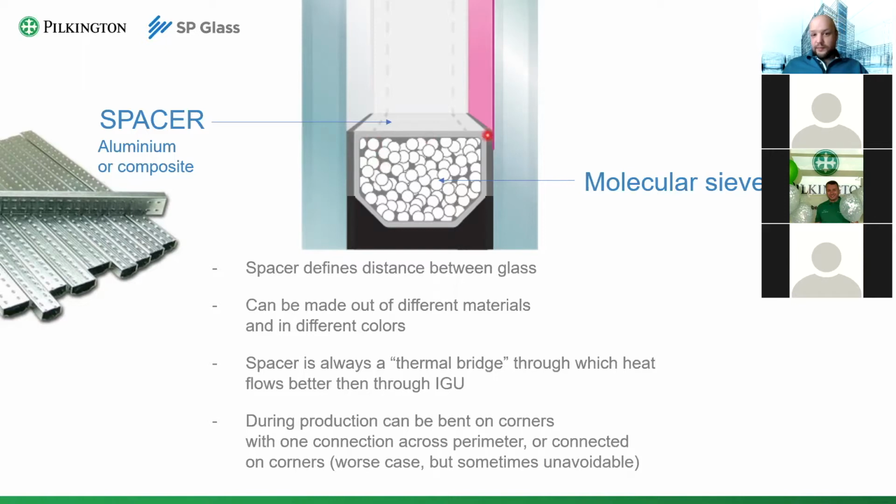Okay, every spacer can be made in different colors, namely black. Again, very useful if you have butyl expansion problems. And butyl expansion problems are a great thing in hot climates when an IG unit can get heated up rather quickly under the powerful sun. So yeah, a black spacer is a good thing, in my opinion.